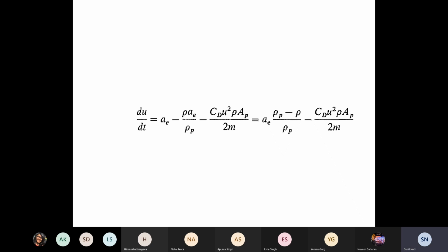In other words, the drag keeps on increasing with the velocity, and so that's a very strong negative force on the settling force due to the gravity, let us say, or the centrifuge. And so somewhere you would expect the acceleration to keep decreasing.